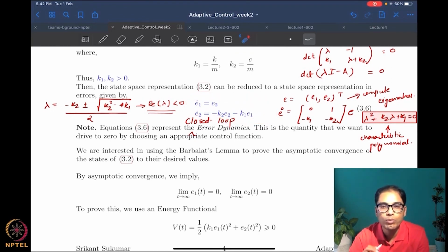But what if I want to prove this using Lyapunov methods or using a potential function? This is what we will see next time can be done using Barbalat's lemma. Why do we want to do this? Because typically nonlinear systems may not have such an easy, nice structure. You may have something very nonlinear appearing here, and then you cannot use the Routh criterion and so on.